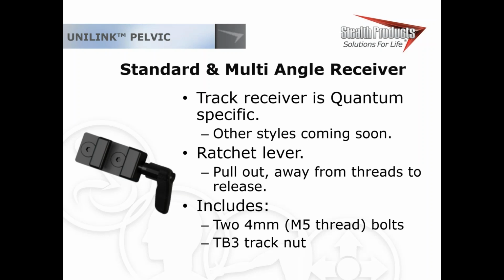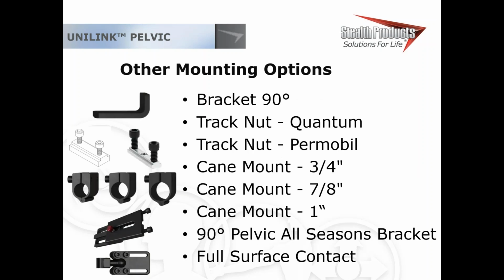For this next launch or release or updated release of Unilink, this receiver has received no changes, so it's exactly the same. My only tip here would be make sure you set that ratchet lever before you mount it to the chair. So put your stem in there, tighten that down, back it off 1/2 a turn, and then install it on the chair. If not, you get stuck fighting that ratchet lever for like 20 minutes.